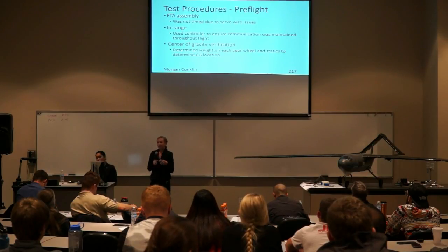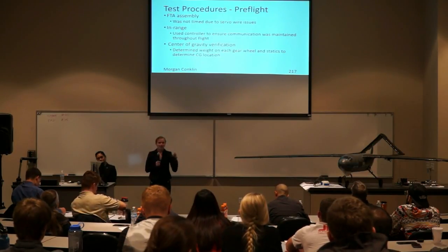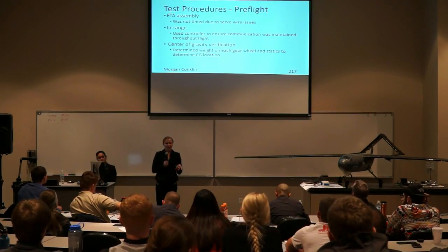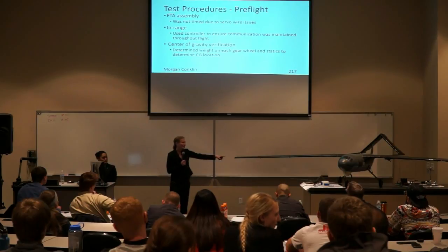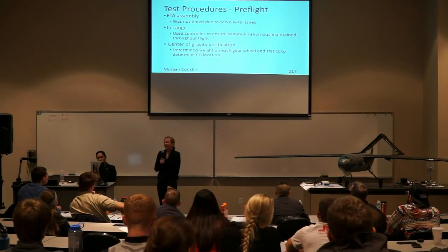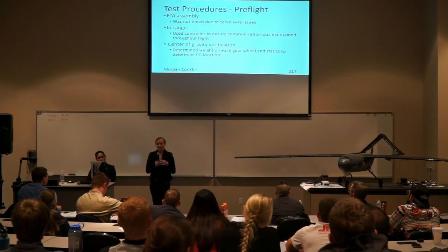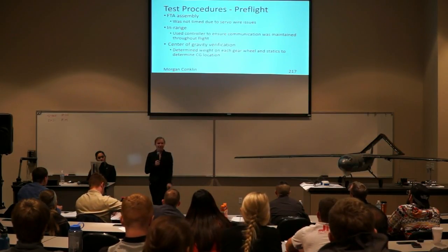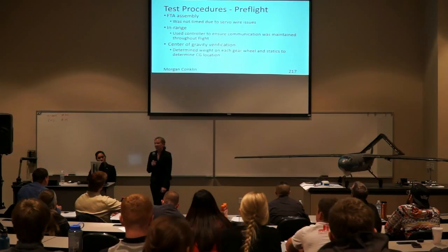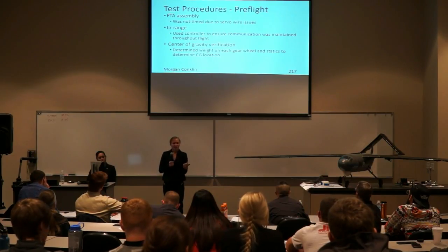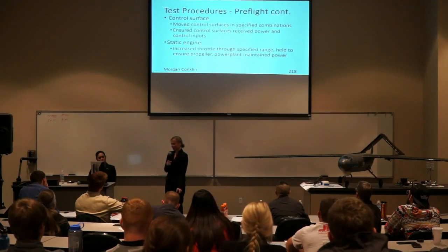For procedures, we did the FTA assembly as Joshua Day previously discussed. However, we didn't time it for the RFP. We were having some issues with the servo wires and the wings. For in-range, we used the controller to ensure that we had communication with the FTA throughout flight. And then we did the CG verification by using the weight on wheels and statics.